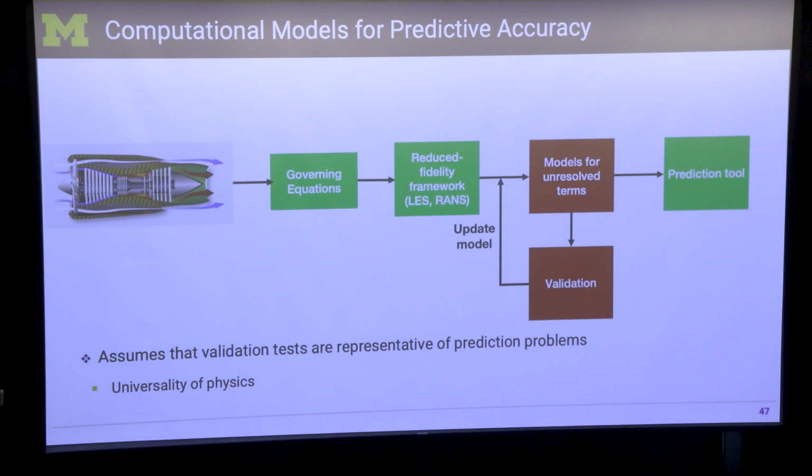Invariably, when you do this reduction, you will find that there's information that's different between the full system and this reduced system. And that difference, you have to somehow model it. This is what is called modeling, combustion modeling or anything else. So that's called models. In this case, it's called unresolved terms. We'll see what this means in a second. And once you put in models, you can no longer trust this implicitly. Like the Navier-Stokes equations, we trust. We don't question whether they're right or wrong.